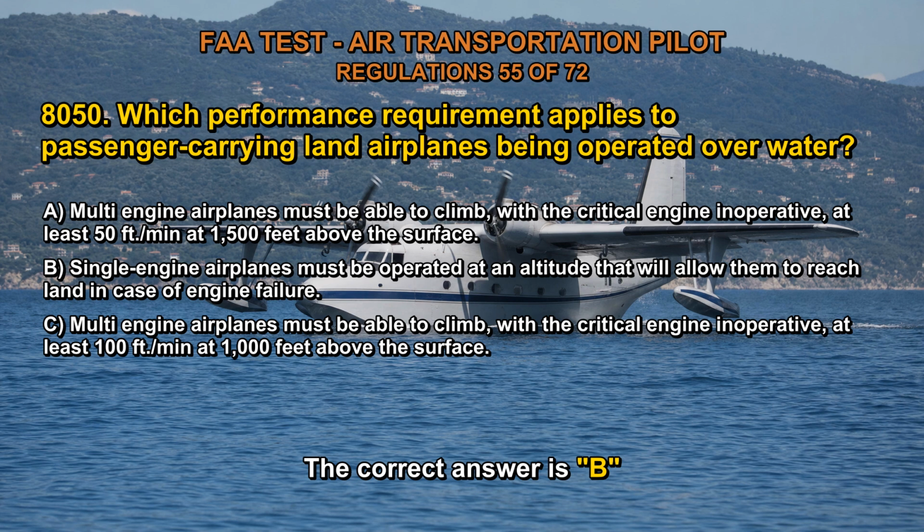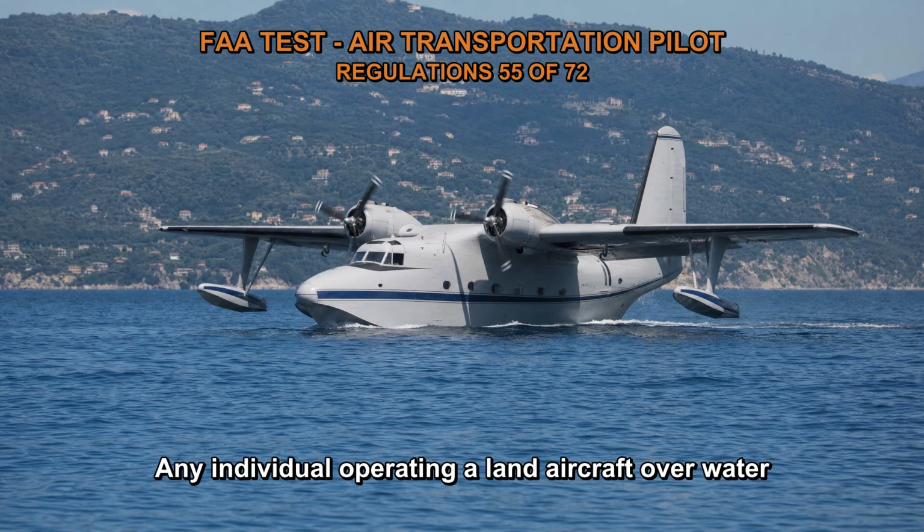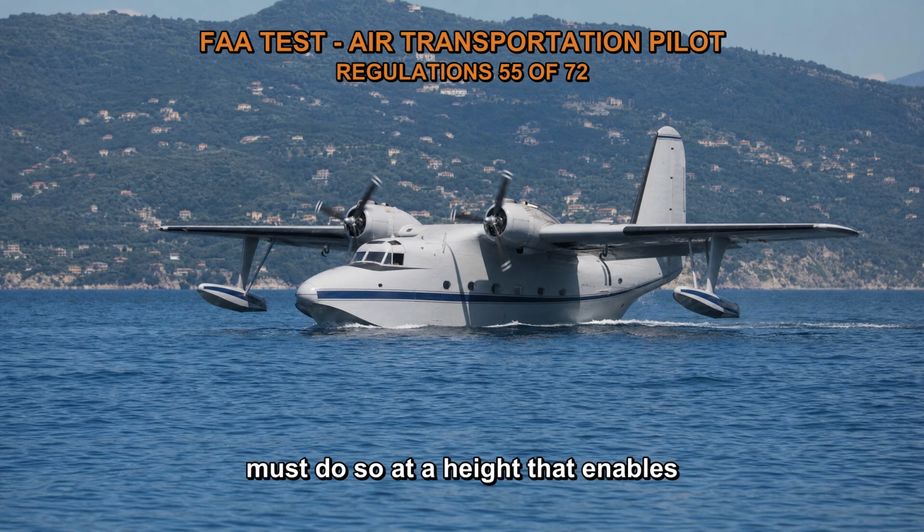The correct answer is B. Any individual operating a land aircraft over water must do so at a height that enables the aircraft to land in the event of an engine failure.